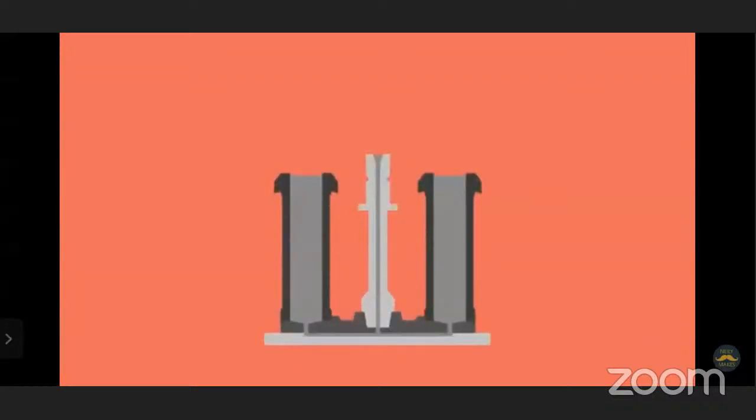Ingots that are uphill teemed use a ladle, either directly or in a teeming car, that is positioned over a feeder system to enable the ingots to be filled from the bottom of the mold. The ladle is positioned over a funnel called a trumpet. It is opened and the metal stream established. The pouring rate is controlled throughout this teeming process.